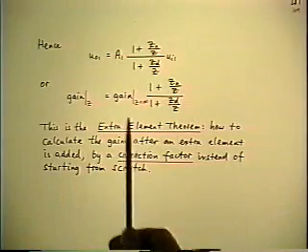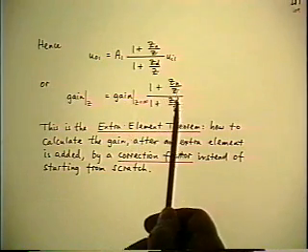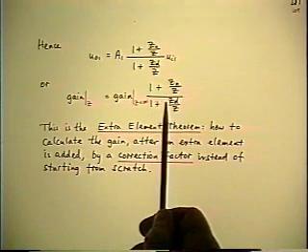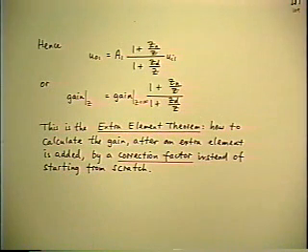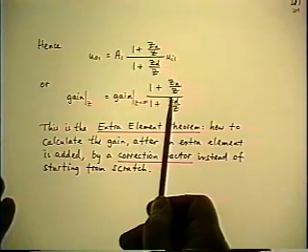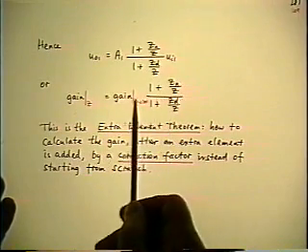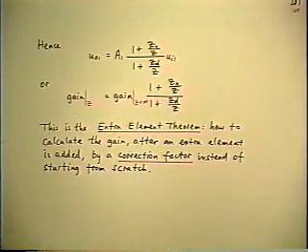So all of the parameters in the formula, the original gain and the 2 driving point impedances, are properties of the original box. And you never calculate anything on the box in the presence of the Z. All you do is substitute into this result, and that gives you the answer, in place of solving the whole system. So that is the extra element theorem.